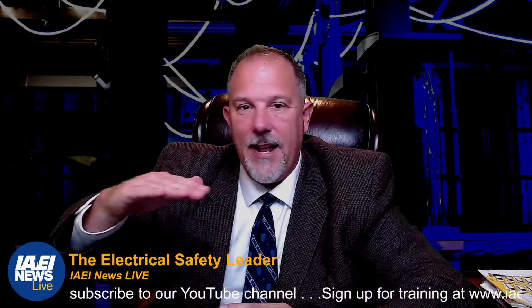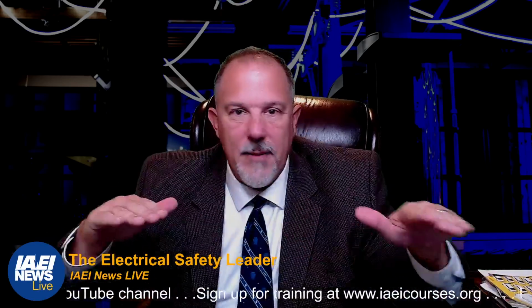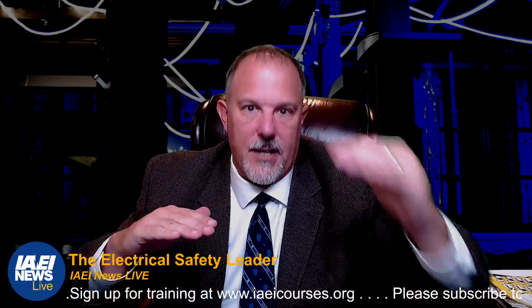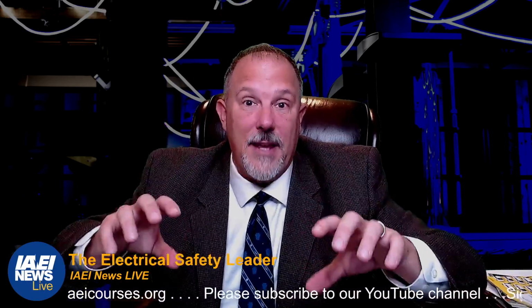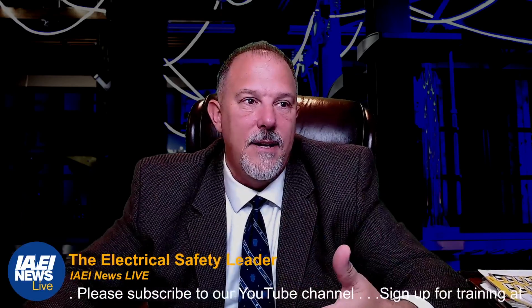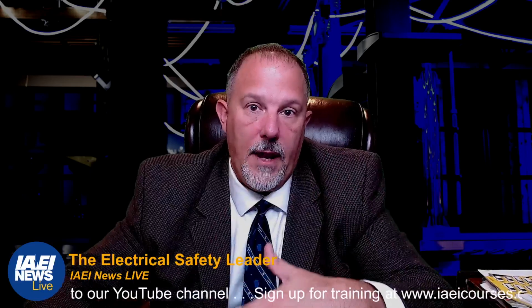So you have 100 amps, and you can use 100 amps worth of conductor. But you don't buy 100 amps worth of conductor. You go to 125 amps of conductor. Remember, the ampacity of the conductor has to handle the amps. You can't say, I'm going to go to the next size conductor up. You pick the conductor for the amps.